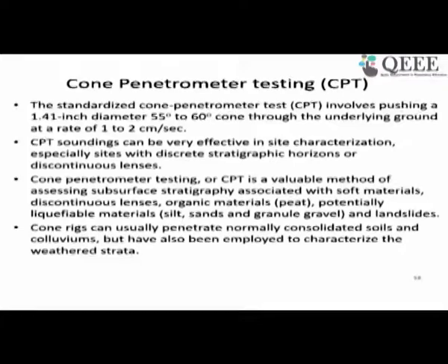What I mentioned here, like where the strata is highly heterogeneous and you need to have frequent SPT testing, going by SPT testing in such kind of strata is really time taking and really difficult and cumbersome. So CPT testing would be much better in such situations.